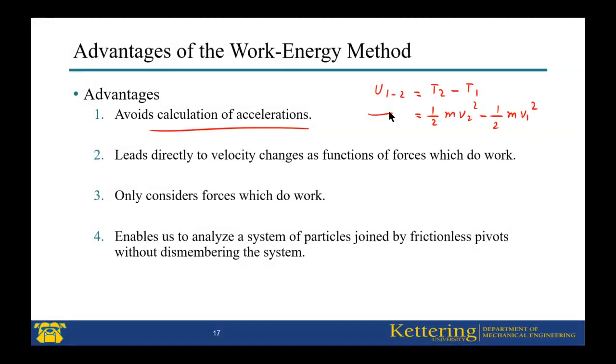Also, we only consider forces which do work. You will see from this one. For example, for a body just moving in this direction, I apply a force F. The work done by the weight and the normal force will be 0. I only need to consider the force F, because this is doing work, not the weight, not the normal force.